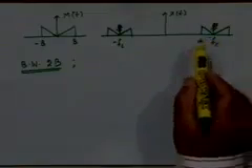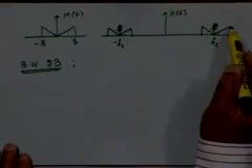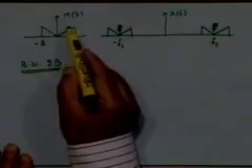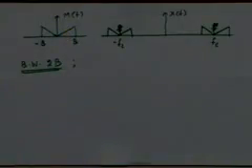Otherwise, when you have a value of a density function which is not impulsive, if you were to ask how much power is carried at that frequency, the answer is 0, right? So you have to understand that issue. There is no carrier component in the suppressed carrier waveform. There is a value of the spectrum at that frequency, surely. It could be 0, it could be something finite, depending on the spectrum of the message waveform. But that has to do with the message waveform. It doesn't have to do with the carrier itself.